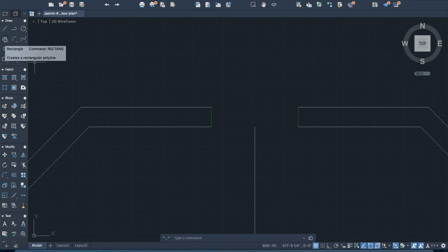Let's go again. Escape. Click rectangle. Start there. So specify dimension. Type D. Specify the length 4 inches. Enter. Specify the width 2 inches. Enter. Let's try again. Specify the first corner, then type D, press enter, type 4 inches, enter, 2 inches, enter. It's going to ask you for the length and the width.